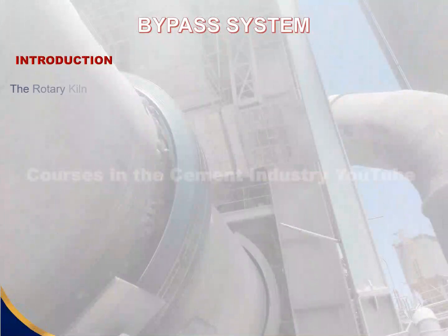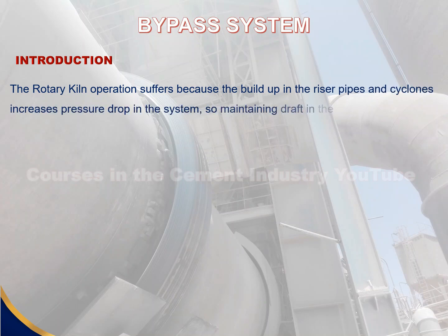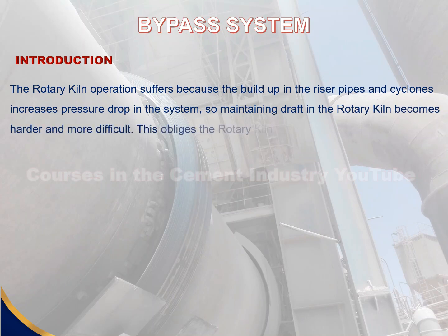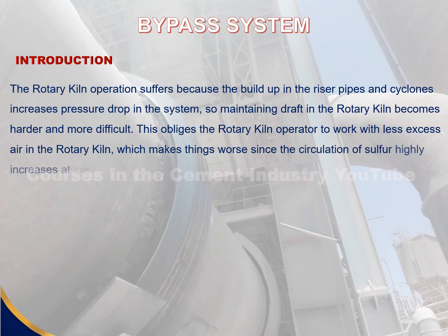The rotary kiln operation suffers because the buildup in the riser pipes and cyclones increases pressure drop in the system, so maintaining draft in the rotary kiln becomes harder and more difficult. This obliges the operator to work with less excess air in the rotary kiln, which makes things worse since the circulation of sulfur highly increases at low oxygen level.